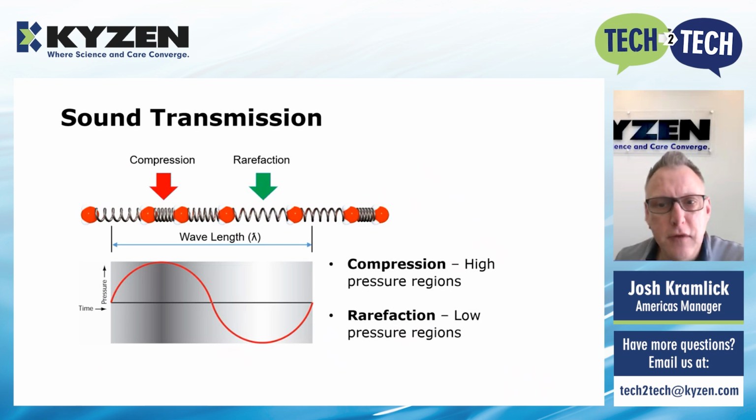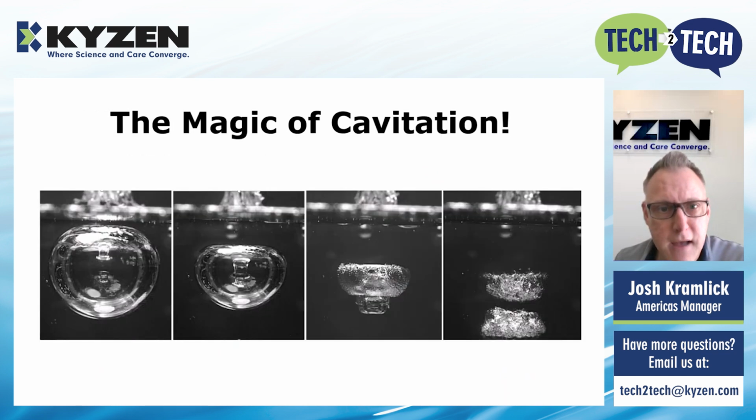It's in these low pressure regions that we create the magic of cavitation. And here in the sequence of photos, you can see the collapse of a cavitation void ending with that very stereotypical microjet burst at the end, which creates the cleaning activity.